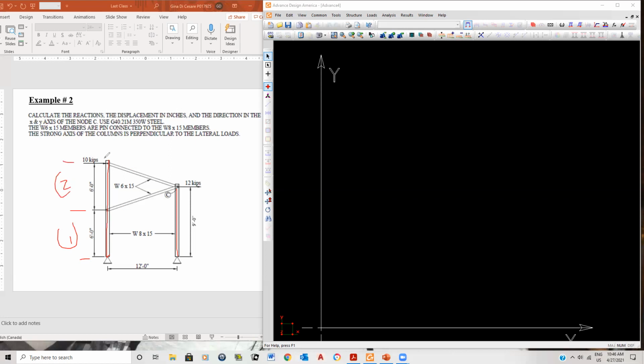So even though this is continuous, and it will actually come to the site in one piece, when you want to model it, you have to model it as if this goes from here to here, and then from there to there, so that this member here can interact with that member. If you don't create a node there, then the program will not be able to have this member interact with that member. And that's what that node does.